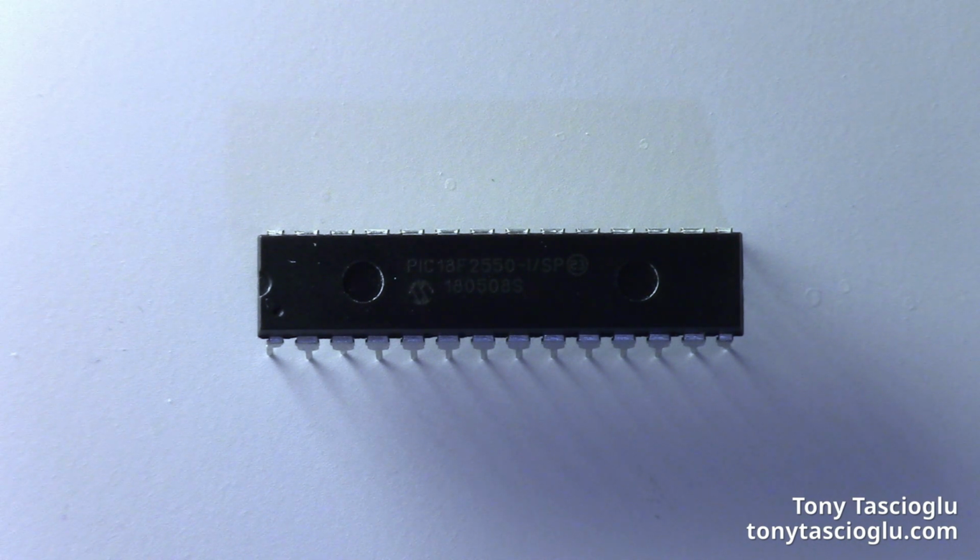This IC has a 12 MIPS 48 MHz processor, 2 KB of RAM, 1 KB dual port, and 1 KB general purpose, 32 KB of flash storage for your program and data. Since it is a microcontroller, there's also plenty of I/O. There are a total of 16 input and output pins.